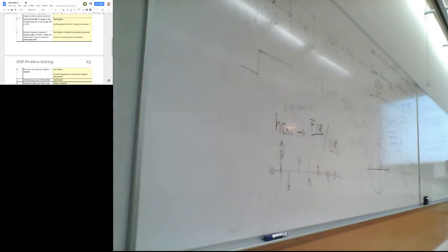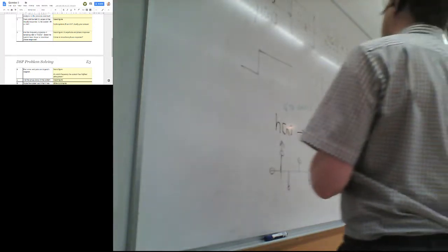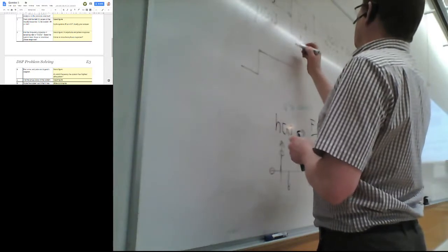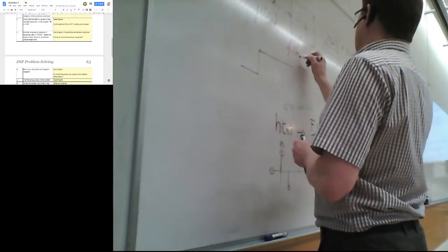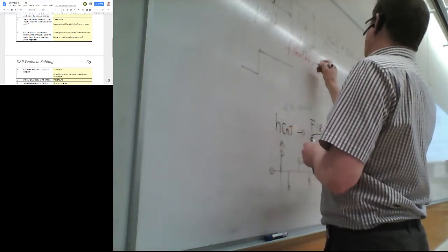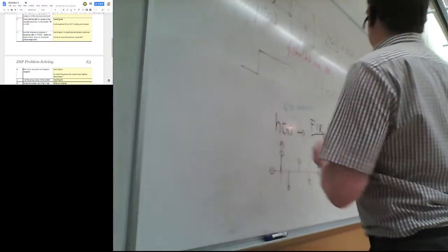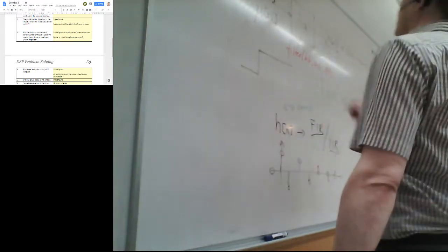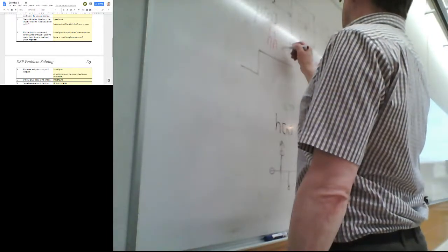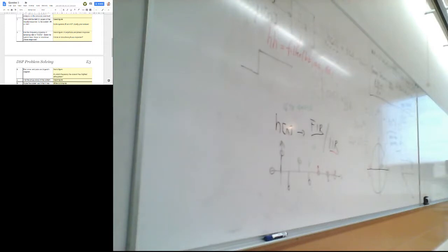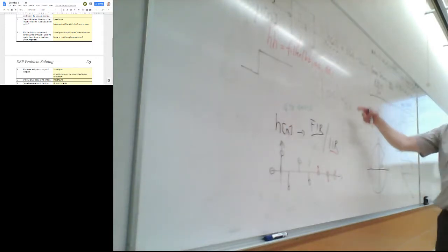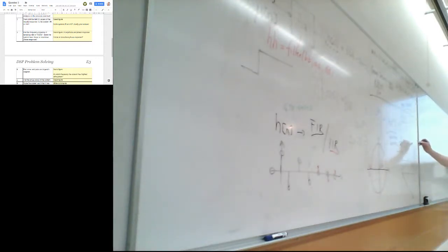So all of that you can get by evaluating the impulse response. In MATLAB, the system implementation is filter(b, a), and then delta in would give you the impulse response. There. The frequency response like that in MATLAB is freqz.